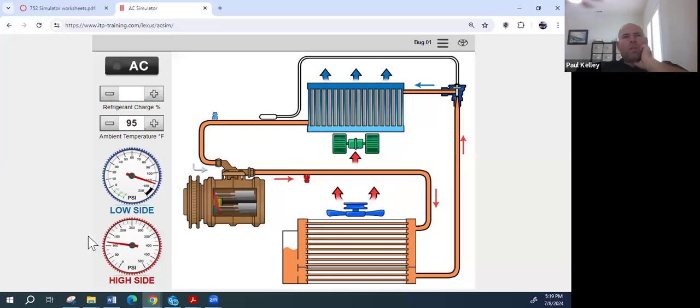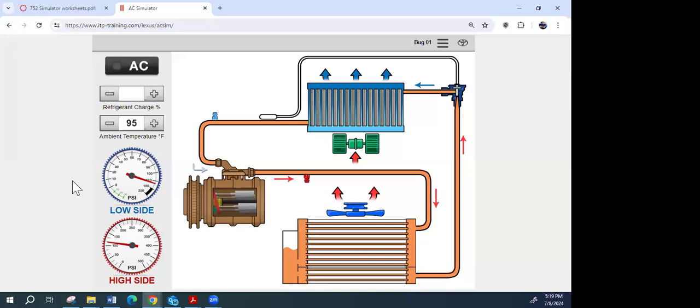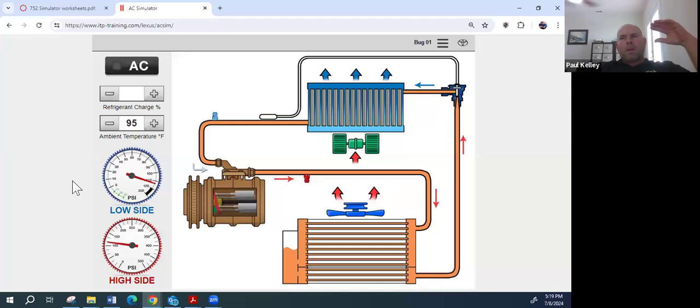We've walked out to the vehicle and we've put the gauges on. Can anyone tell right now if I have the AC turned on or off, or what do you think? AC is not on. I agree. So we could begin with any different types of diagnosis you want, but typically it's a good idea to start, if it's a customer car, one of the first things you could do is check to see if it works. Would you agree? So we would jump in the car, we put on the AC.